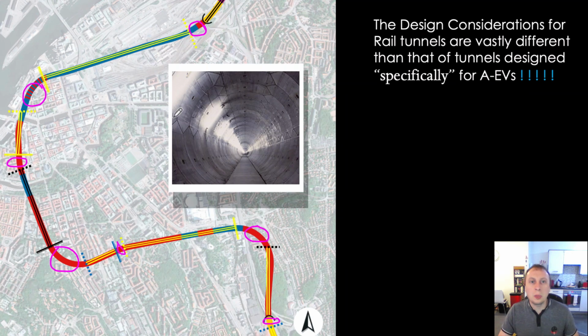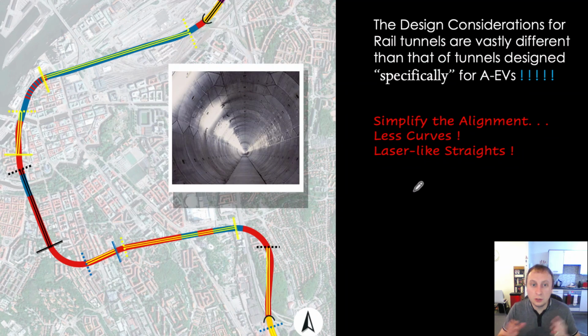As you can see, around 85% of this tunnel, if it were to be built, is hexagonal segments. These areas here, the 20%, is rectangular segments. So it is going to be slower in the corners, but I don't need to worry about aligning my segments, and what I gain from doing that gives me greater speed down the road using my hexagonal segments. So I'm going to simplify the alignment. I'm really going to focus on making this tunnel much straighter than a traditional rail tunnel.